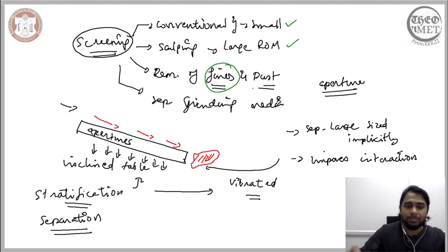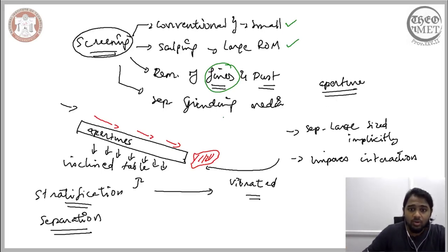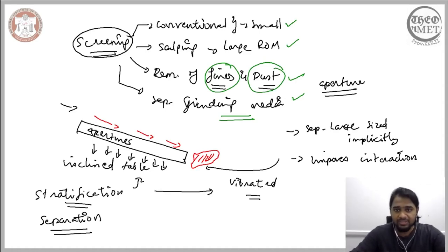The same goes for separating the grinding media. Once we arrive at the yield of the grinding process, and we are sure that the reduction ratio we desired is achieved, we use a technique similar to screening in order to separate the grinding media from the mineral particles. Similar to the dust, which is an external agent found in the mixture of minerals rendered by the different comminution processes, the grinding media are also external agents.